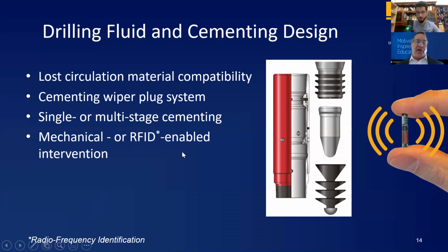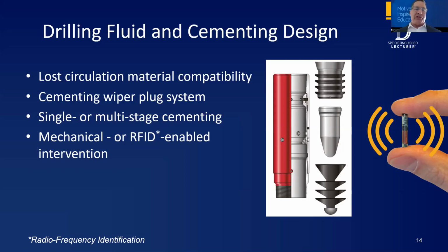RFID tag. The beauty of this, especially with stage collars, is that there's no pressure surge when you open the stage tool. And this is especially valuable when you're adjacent to a low pressure or a tight pressure window, or any pressure surge could potentially break down the formation. So just something to think about in design of cementing and drilling fluid.